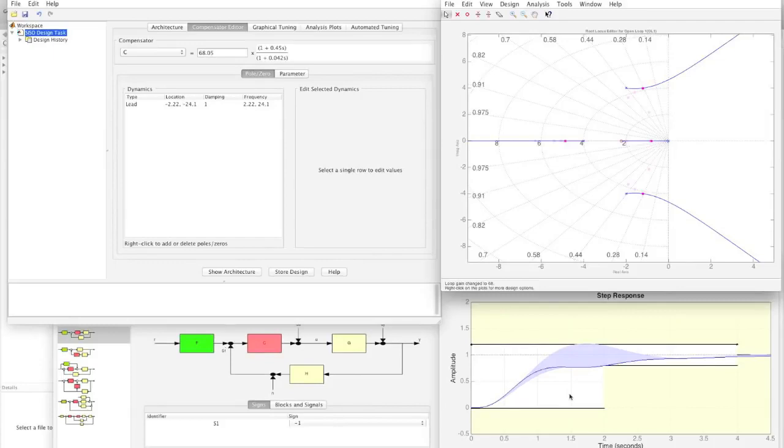Now I think if you play around with a couple of transfer functions and the SISO tool, you'll gain a better understanding of what the root locus plot looks like for various systems, as well as how adding poles and zeros affect the shape of the plot. Also, you get to see real time the effect your compensator design has on the response of the system.